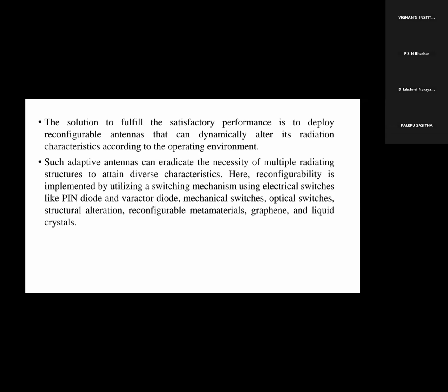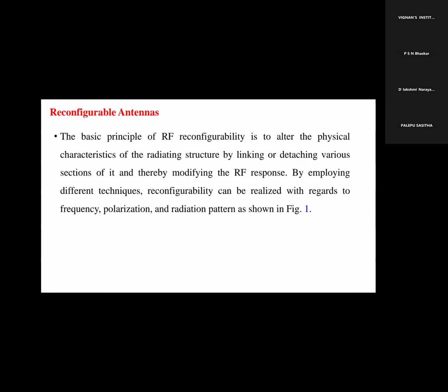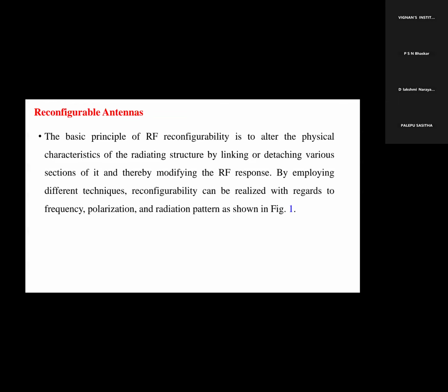Here, the reconfigurability is implemented by utilizing a switching mechanism using electrical switches like PIN diodes, varactor diodes, mechanical switches, optical switches, structural alteration, reconfigurable metamaterials, graphene, and also liquid crystals. So first we will discuss what is the meaning of a reconfigurable antenna. The basic principle of radio frequency reconfigurability is to alter the physical characteristics of the radiating structure by linking or detaching various sections of it, thereby modifying the RF response. By employing different techniques, reconfigurability can be realized with regard to frequency, polarization, and radiation pattern, as shown in the figure.